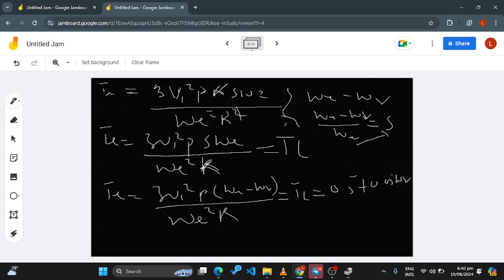So then people are saying, why are we still converting it to mechanical speed? The issue is that the omega r here and the omega r here are not the same. They are similar, they are all rotor speed. But this one is in mechanical speed, and this one is in electrical speed. And we know there is a relation between mechanical speed and electrical speed.